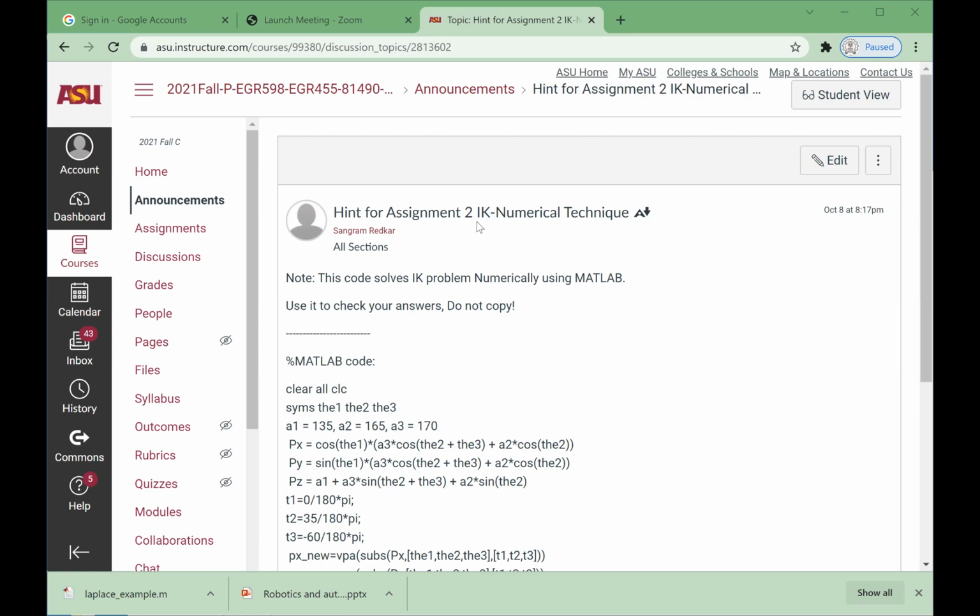You have 3 joint variables, just like this problem. The first joint variable is the angle theta 1. The second joint variable, since it's a prismatic joint, is the distance d2. And the third joint variable, since it's a revolute joint, is theta 3. Any other questions here?